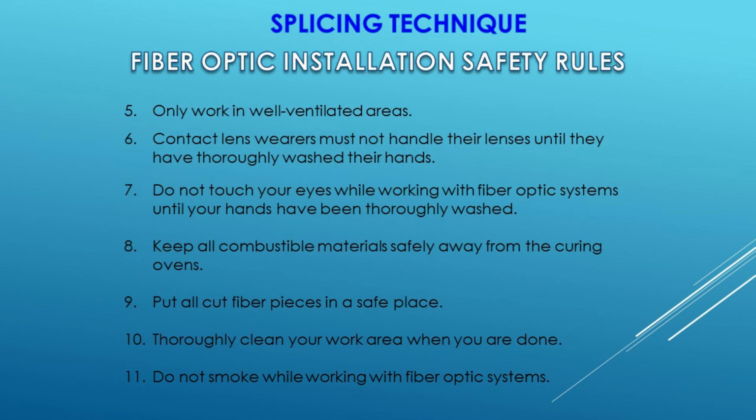5. Only work in well-ventilated areas. 6. Contact lens wearers must not handle their lenses until they have thoroughly washed their hands. 7. Do not touch your eyes while working with fiber optic systems until your hands have been thoroughly washed. 8. Keep all combustible materials safely away from the curing ovens. 9. Put all cut fiber pieces in a safe place. 10. Thoroughly clean your work area when you are done. 11. Do not smoke while working with fiber optic systems.